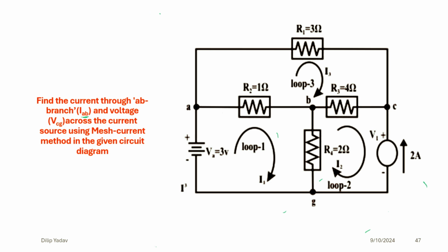So for example, I take this loop as my first loop. So this is the positive terminal, this is the negative terminal. I will start from this point. I said this was the current that was flowing, that was I1, and this was the current that is coming inside it, this is I3. So I will write R2 (I1 minus I3), coming at this point we have come to B point, before that we have this R4, and the current is going in this direction.